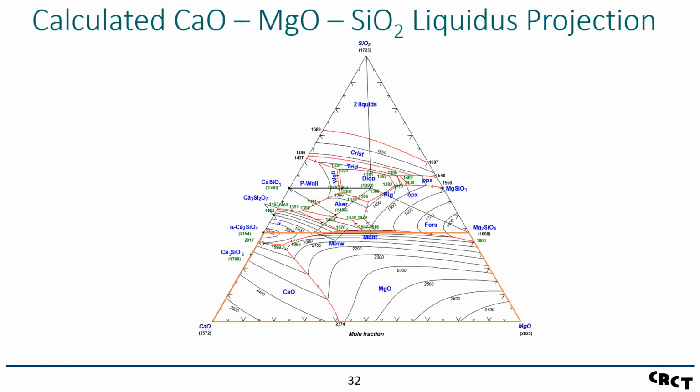And here we have the calculated calcium magnesium silica liquidus projection. Here we had 2 small ternary terms, and we've managed to reproduce the diagram within the experimental error limits. And we've done this for many, many ternary systems. Even without the ternary terms, you come pretty close.